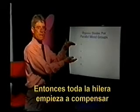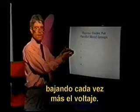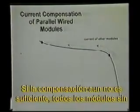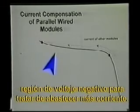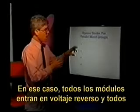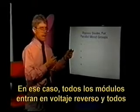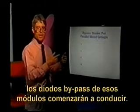So the whole string begins to compensate by going lower and lower in voltage. If the compensation is still not enough, all of the unshaded modules will actually pass through their short circuit point and go into a region of negative voltage to try and supply more current. In that case, all of the modules will have gone into reverse voltage, and all of the bypass diodes of those modules will start to conduct.